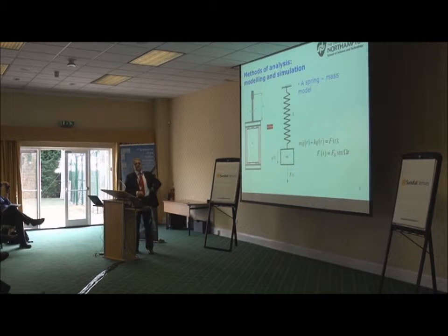This is a simple possible model which you could use. We refer to this as a single degree of freedom model. Namely, you have one mass, and the position of this mass can be defined by one parameter. It is here Q, which could be displacement in meters, for example. So a spring-mass model can represent a lift car suspended on hoist ropes. Simple representation and very effective when we want to do some calculation or modeling to identify qualitative behavior of the system.